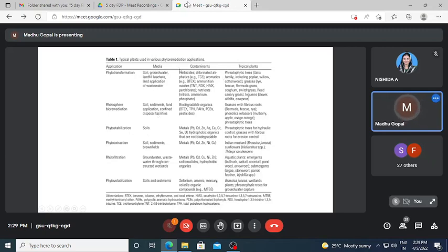As far as organic chemicals are concerned, we have techniques like phytotransformation and rhizosphere bioremediation. So these are the contaminants usually that can be removed from soil or groundwater, herbicides. It is applicable even for landfill leachate. In engineered landfill systems, we collect the landfill leachate. That landfill leachate may contain all these substances, so we can treat this landfill leachate using these technologies.